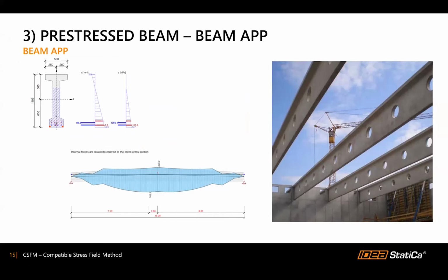The first aspect is that we'll be using time-dependent analysis. For beams like this, which are pre-stressed, it's essential to have the construction stages, because the concrete is undergoing aging, which means it's changing the material properties during the whole life of the structure, and you need to catch the stages which are important for checking.